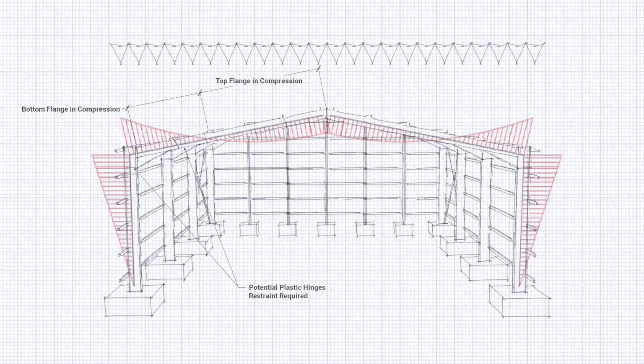Elastic-plastic design would be the most economical for the design of a portal frame, as it considers both elastic analysis, which looks at the frame in the elastic state under our service loads and deflections, and then plastic analysis, which looks for plastic hinges that will develop in the frame under our ultimate loads that will cause collapse. So that's effectively a strength design. Where deflections, i.e. serviceability, govern design, there may be no advantage in actually using plastic design for the ultimate limit state design. If stiffer sections are selected in order to control deflections, it's quite possible that no plastic hinges form and the frame remains elastic at ULS.